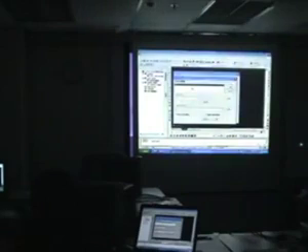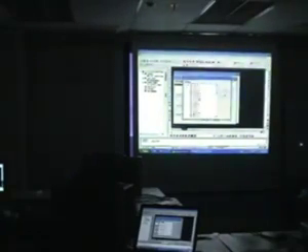Now the third one, I'm not going to take z, because if we take a z value of the text, we're actually taking the absolute value of that z, which means, for example, if the text was placed at 0, we're going to take 0, which is pointless. We don't want that. What we want to do is take the text value. If it's 44.59, it's going to appear as 44.59. That falls under the property string. String. Yes, it's under string.